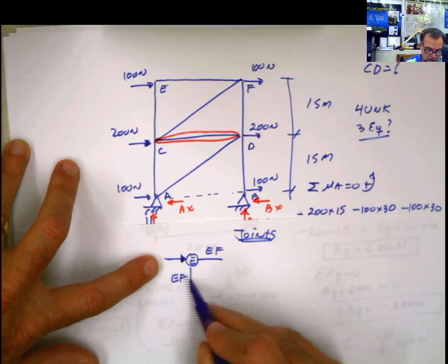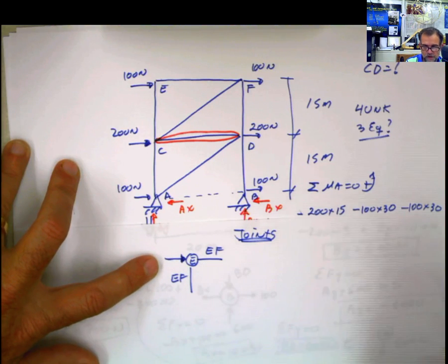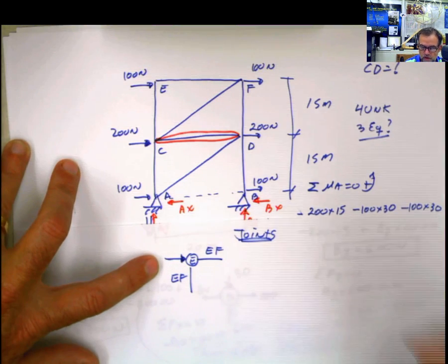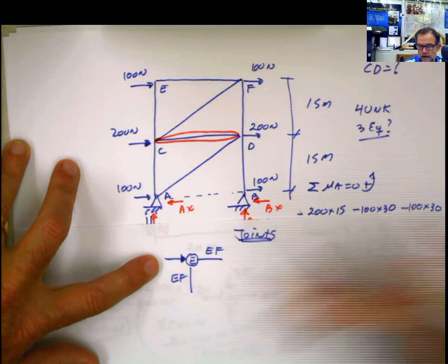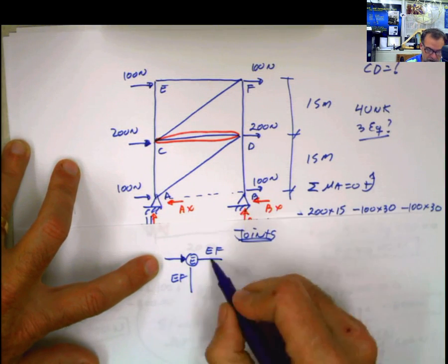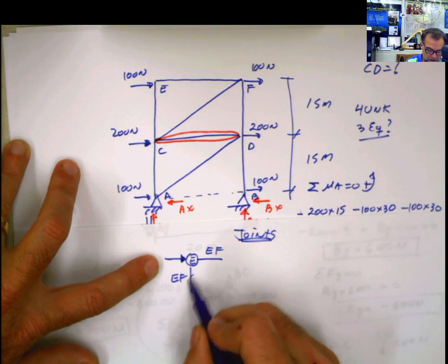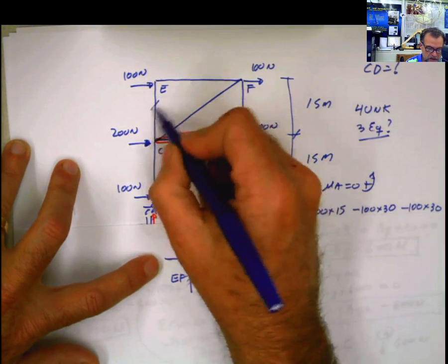The first thing that you should realize is here, you have 3 elements because the force is considered like an element. Remember when I explained the zero force member rule, I said 2 forces, 3 forces, or 3 bars, or any combination of forces plus bars. You have 3, which is one of the rules, and 2 of them are collinear, so that means that the one that is not collinear is 0. That means that this bar is 0.